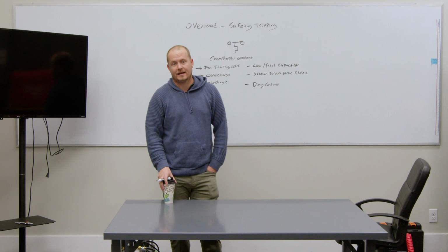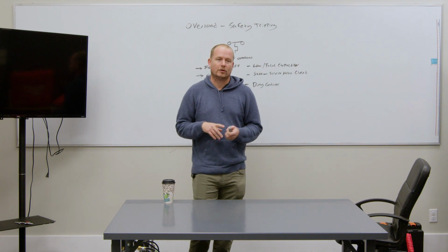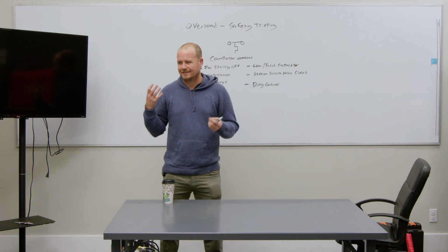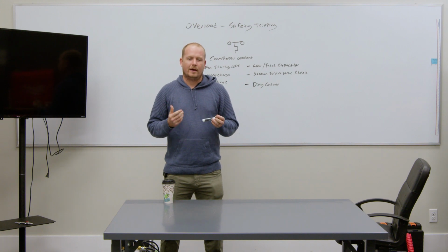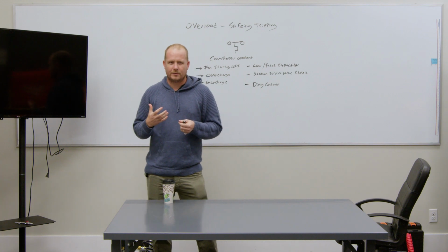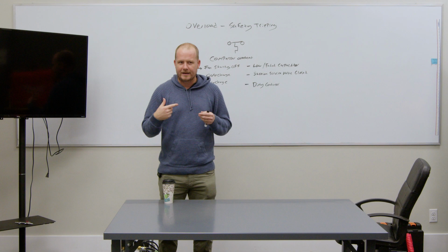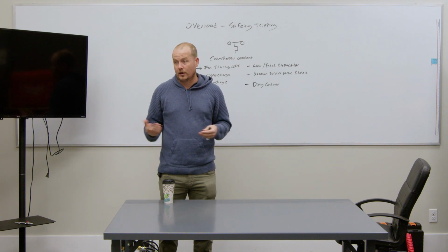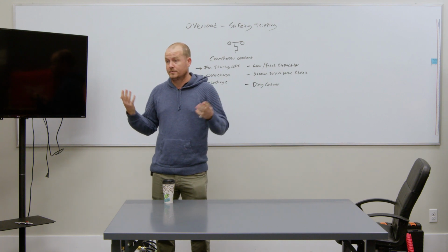Okay, so the reason is that the condenser fan motors they used were clamshell motors. They were low horsepower motors, I think like a sixth or an eighth horsepower, something like that. And they would just go out on overload. I think it was probably bearing failure, but it wasn't instantaneous. It wasn't like it would be completely locked. You could still spin it. It would just overload on hot days. It may have been something in the design, how it was dissipating heat, who knows, but they would just overheat.